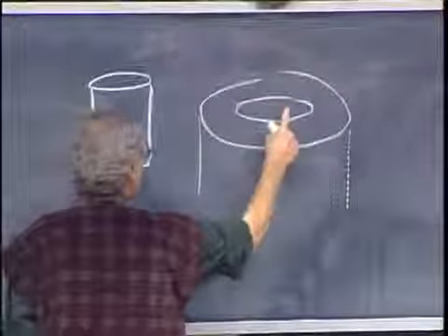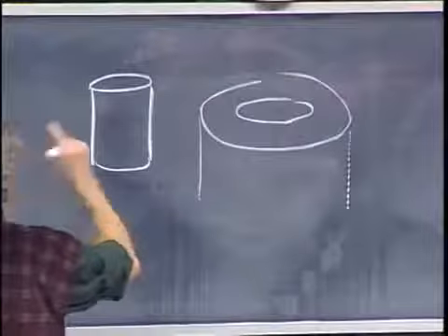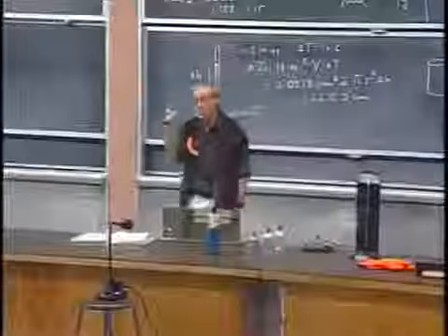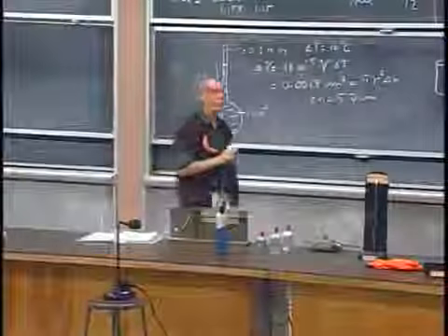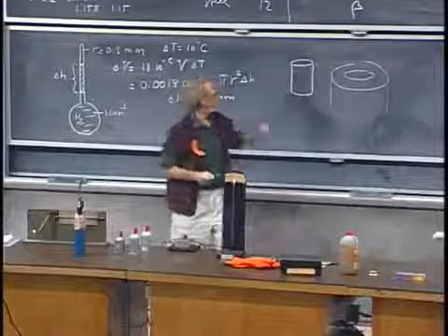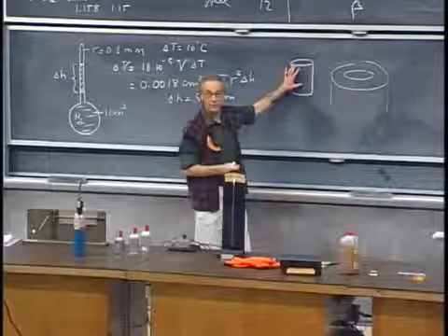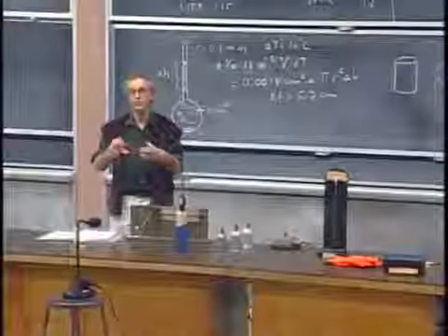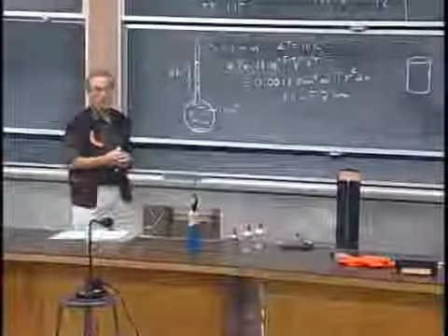This one, this opening, is smaller than this. Just a little smaller. Purposely made that way. You heat this one, it expands, and then you put it over here, it will fit, and then you let it sit, it cools, and it tightens itself up. That's called shrink fitting, a technique which is often used.